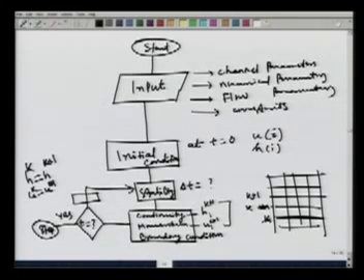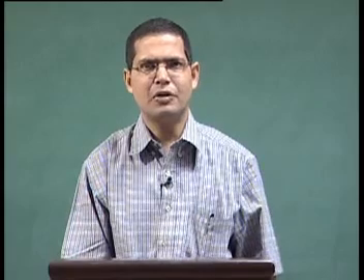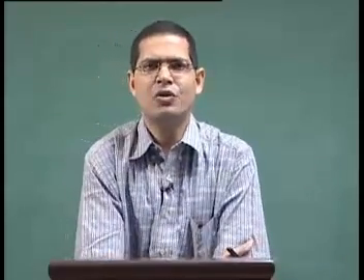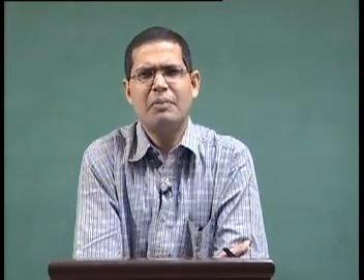So, I time step this. That means I go to one time level, another time level, another time level, like this, and I will stop when I reach the required time level. For example, suppose there is a flood in a river and I know that the flood takes, let us say, 4 hours to reach the downstream end. Then probably I should do the flood routing for 4 hours or maybe 10 hours, something like that.